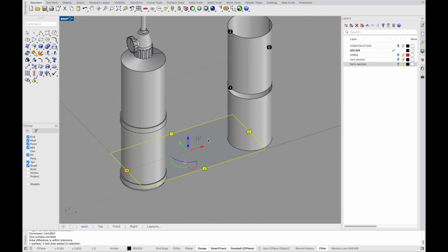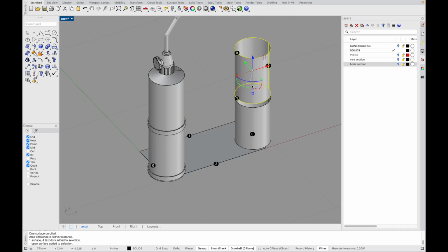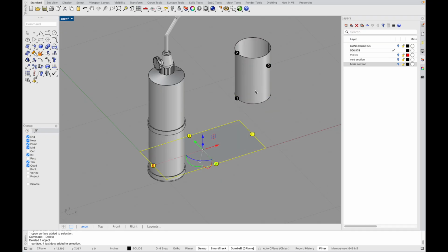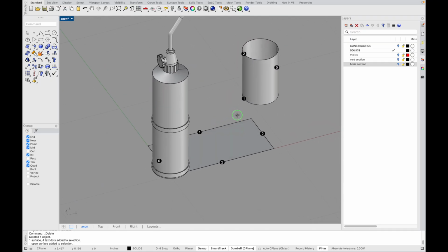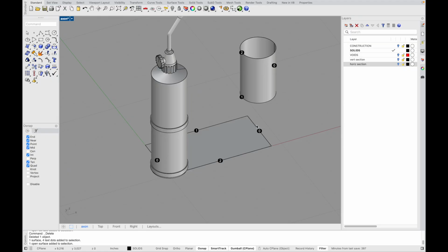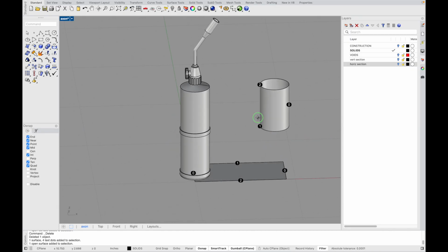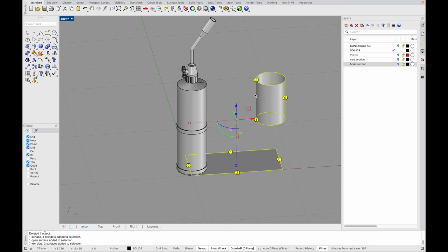what this is going to do is it's going to unroll that surface for me and tell me how to make them, right? So this surface down here is this surface up here. Now I selected an option to label all this stuff, and the reason that's helpful is because it tells me that this edge here, 0, aligns to this edge here, 1 is that edge, and 2 is that edge. Now for a cylinder, I mean, you can just do the math like we talked about.